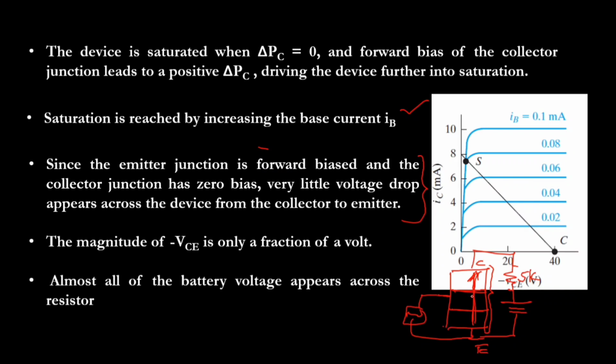So when we apply a positive pulse, the emitter junction is going to be forward biased. Immediately, holes start diffusing towards the base region. The excess hole concentration becomes more here, and near the collector you can see a 0 excess hole concentration. Before, it was less than 0 because of the huge reverse biasing condition.